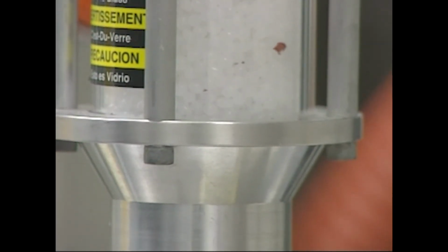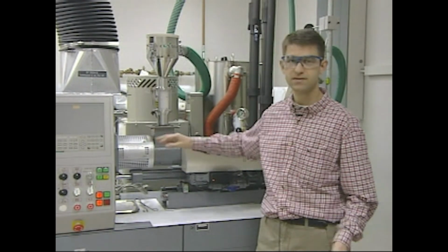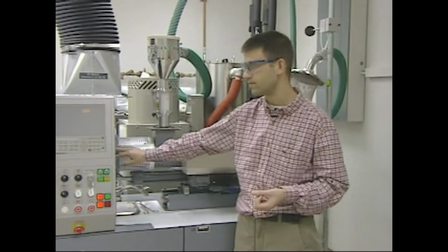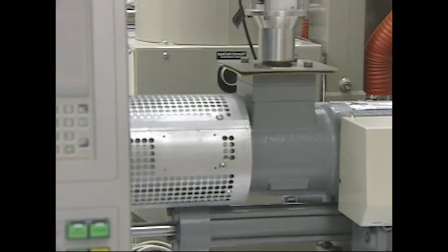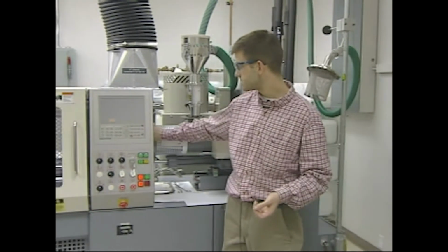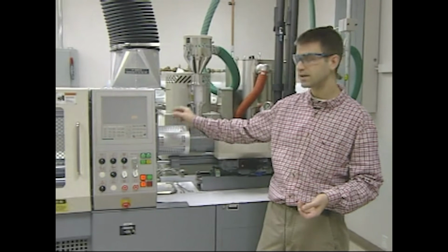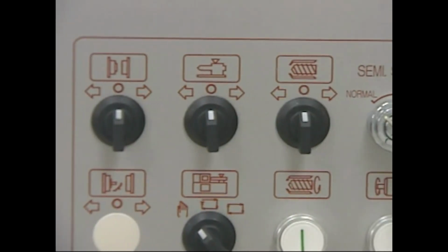That material is then fed down through the barrel by a screw and is pressurized with shear pressure, or shear forces, and there are also heater bands along that barrel. The heater bands and the shear force melt that material and make it into a liquid or molten plastic. That plastic is then pressurized and squirted through the nozzle of this machine out into the mold, which is over here on the clamping unit. As I said, this is a 40-ton machine. That means it's using 40 tons to hold that mold together.